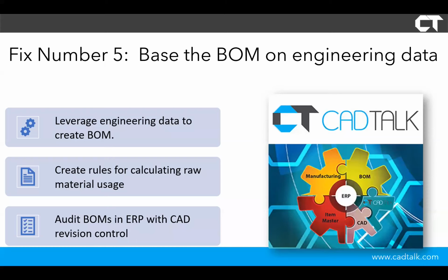Even people who haven't used CAD Talk can still use that data from their model to say, okay, is this particular item a sheet metal good? If it's made from sheet metal, then I know it goes to the laser or the plasma. Maybe it goes to the bend shop. If it's extruded material or it's channel or pipe, maybe it goes to the saw.